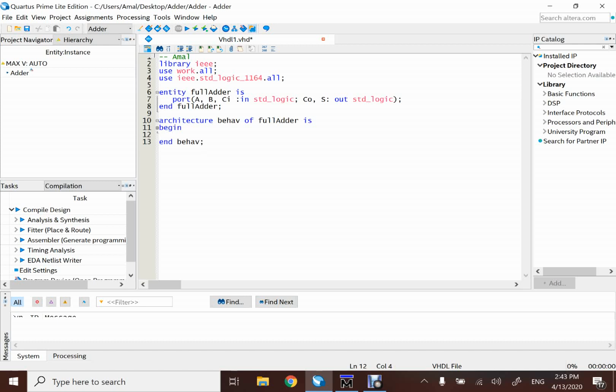In here, I'm gonna define each of my outputs. I have two outputs. The first is Cout, and then I have S. So I will say S, which is the sum bit. Remember, this is the assignment operator. So S is assigned a value equal to A XOR B XOR Cin, according to the logic diagram of the full adder. And then I need to define my second output, which is Cout. Cout is assigned a value equal to Cin and (A XOR B), or A and B. Remember that each parenthesis you open, you need to close, so be consistent with that to avoid any syntax errors or compilation errors.